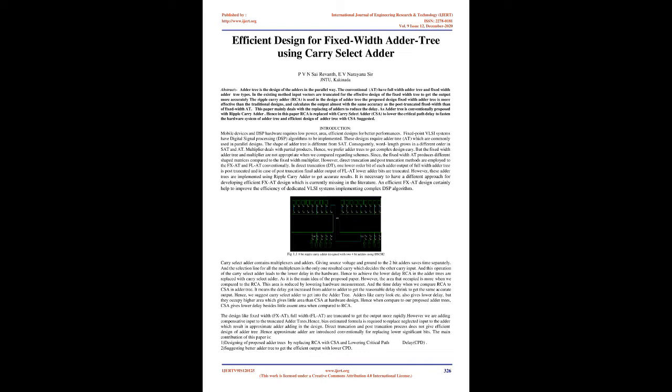In the existing method, input vectors are truncated for the effective design of the fixed-width tree to get the output more accurately. The ripple carry adder, RCA, is used in the design of the adder tree. The proposed fixed-width adder tree is more effective than the traditional designs, and calculates the output with almost the same accuracy as the post-truncated fixed-width and fixed-width ED.